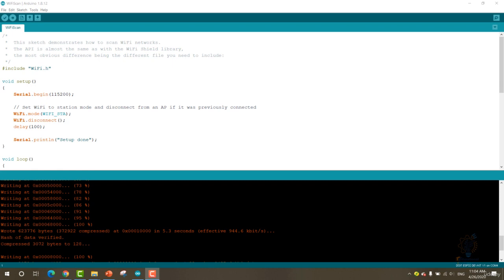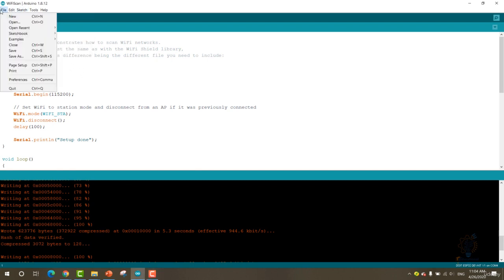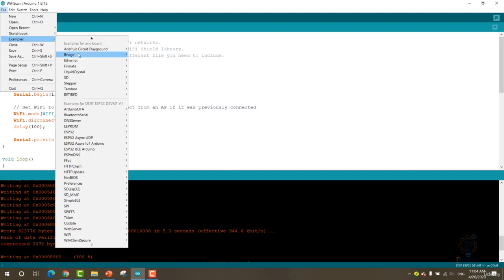As usual, the first thing that we do when we start exploring a new hardware is to blink a LED, or to write a programming sentence which is hello world. In case of our hardware, which is ESP32, the example will be LED blinking. So let's go to the examples menu in the Arduino IDE and open up the sketch example or blink example.